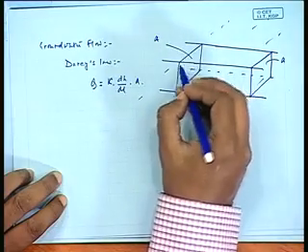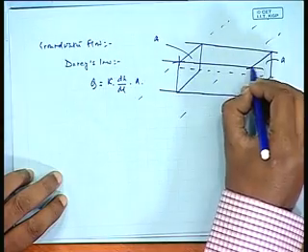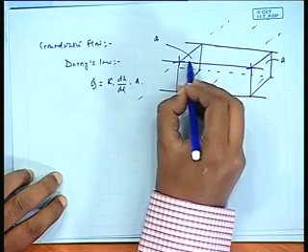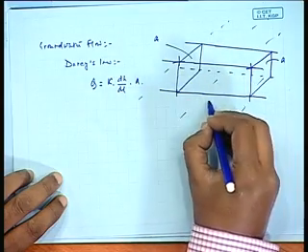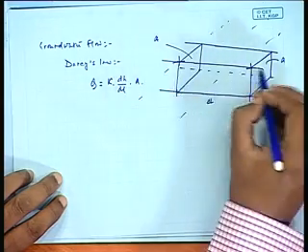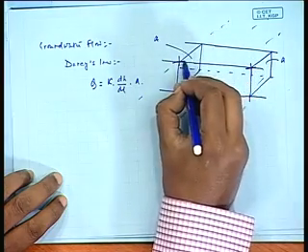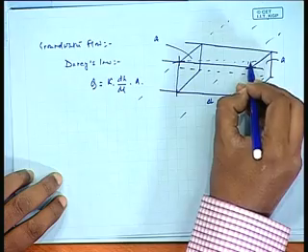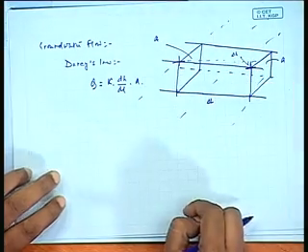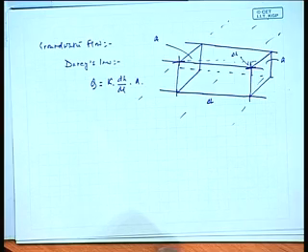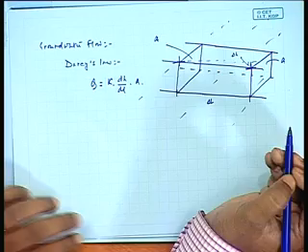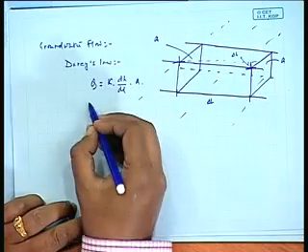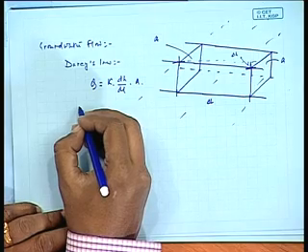This is the L, del L, between this point and this point. This would give you the hydraulic gradient, and this would give you the del H, the difference of the water level in the aquifer. Del L is known, area is known, and the quantity of flow, this is the flow quantity, this is Q.